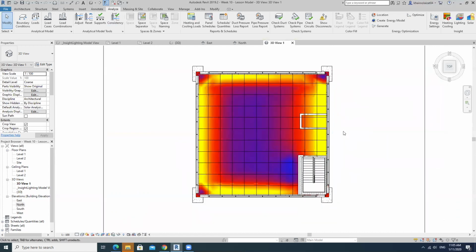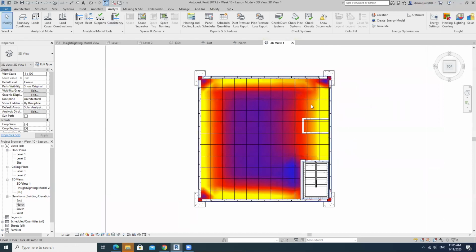Yeah, so from this plan, you can basically see that the east orientation absorbs more energy. So perhaps you might want to, I don't know, place a PV panel at this area as well. Because when you have a lot greater solar radiation, of course, you're going to have a lot of heat penetrating to the surface. So in this case, when I analyze this plan, I can see that the east orientation absorbs a lot of heat from the timeline from January all the way to November 2020.